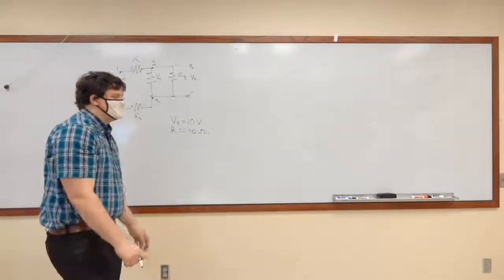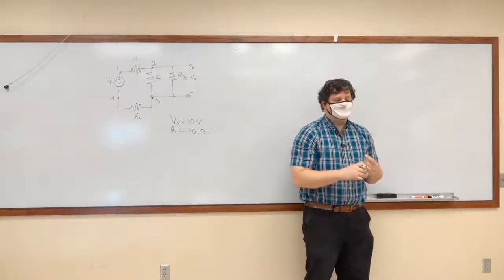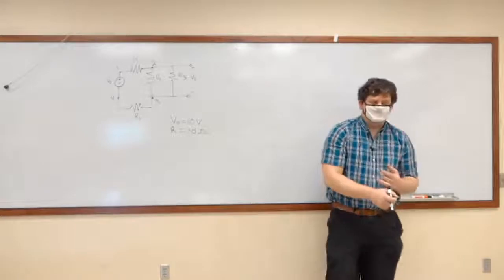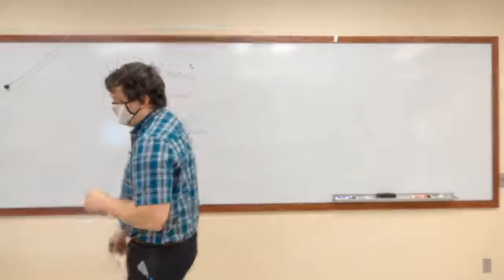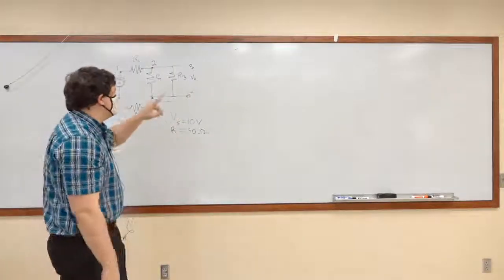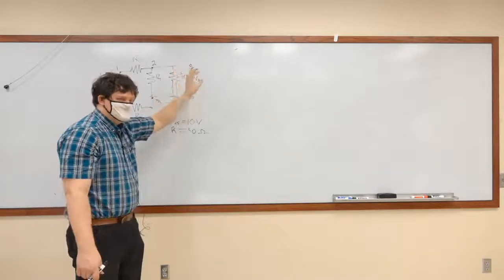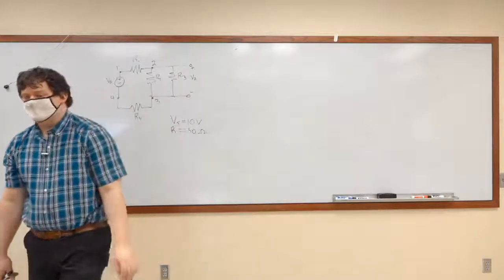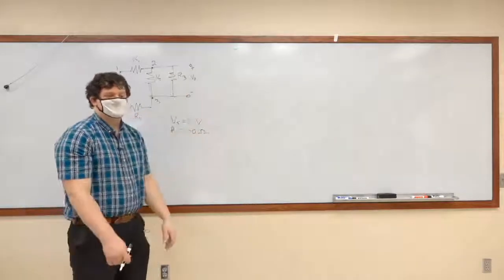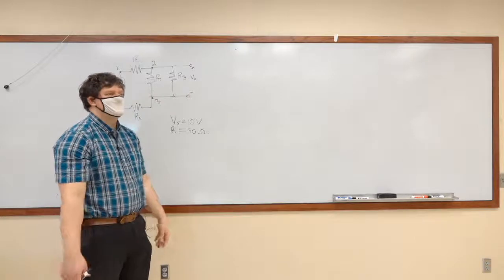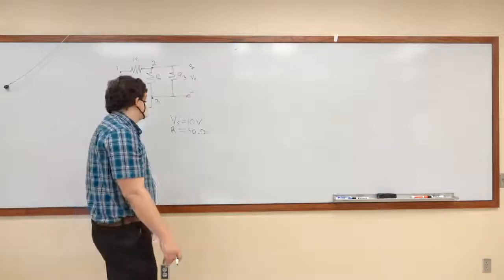Now, if you remember, what we talked about extensively in the last lecture was that it has to have the same open circuit voltage, and it has to have the same short circuit current, which means we're going to have to analyze this circuit as if there was an infinite resistance resistor here, and if there was a zero resistance resistor there. Okay? An infinite resistance resistor, by the way, just kind of filters out. Act like it's not even there, which is not shocking because there is nothing there. It's almost as if nothing is a part of that circuit over there. Oh, because there's nothing there.